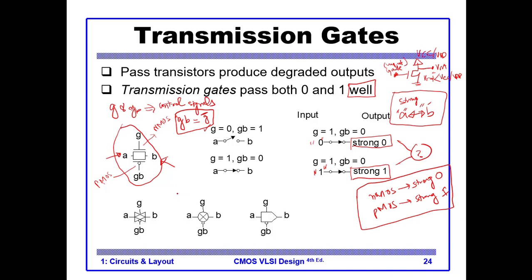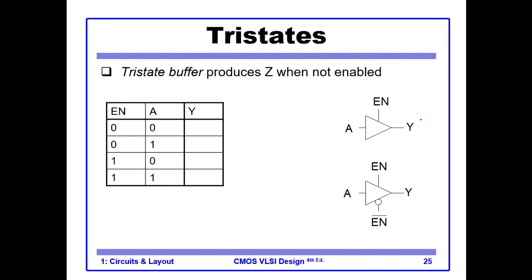Okay, so that's why we said that the NMOS passes a strong 0 but a weak 1. And in the case of pass transistor, this cannot happen because there is no degradation across the transistor. We just connect two signals together. They are just two wires connected together. So whatever is the strength here, the strength is transferred to the other side. So that's why the pass transistors, transmission gates are good, and they pass strong 0 and strong 1.